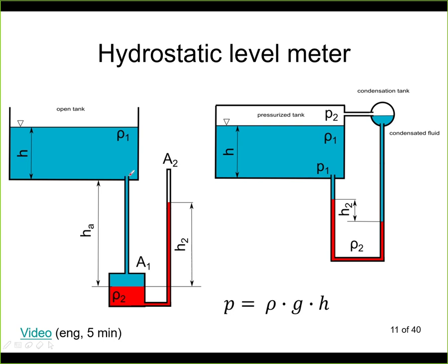Now obviously this will not work properly if you have sediments in the liquid. So if your liquid will create sediments at the bottom or at the walls, this is not a good idea to use this kind of sensor. This kind of sensor can be used if you have foam, but it cannot be used if you have sediments in the tank.